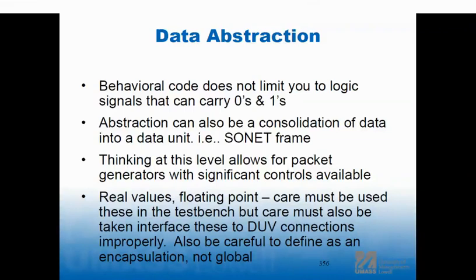So how do you make this decision? Well, the first answer is it might not matter, but the real answer is you kind of go with the system architecture. So when I start thinking about Ethernet packets, for example, I think of all of the fields in the Ethernet packet, and I think if I was actually building an Ethernet media access controller, a MAC, and I wanted to send a packet from one to another, the processor, the thing that was writing the packets that were going to be sent, would write it in a big record, the bunch of fields that I've been saying all day, say, I'm ready.